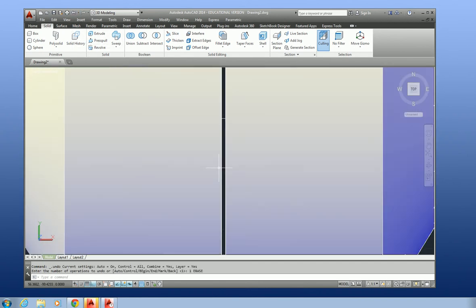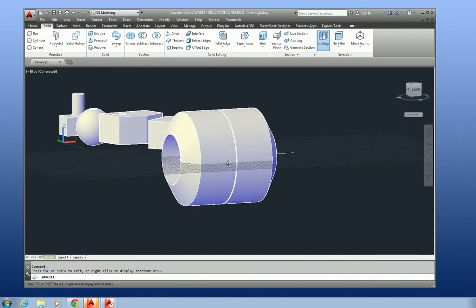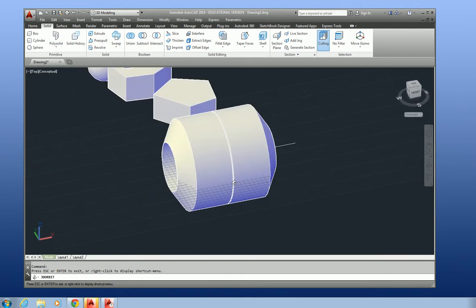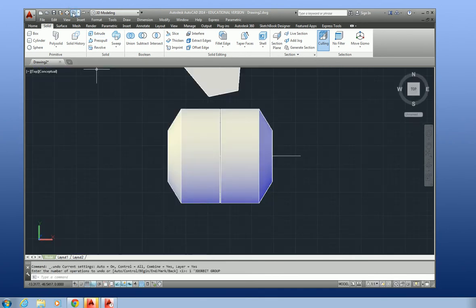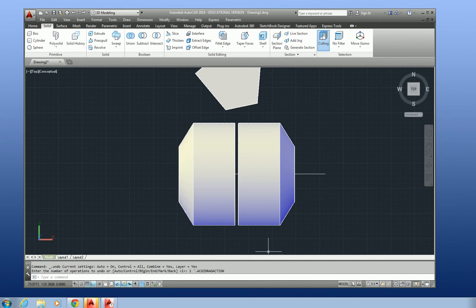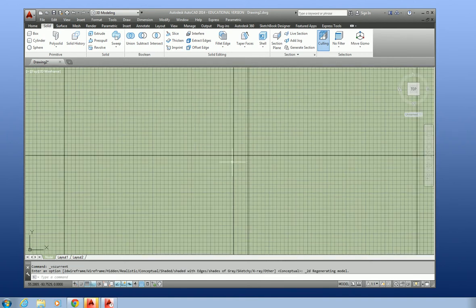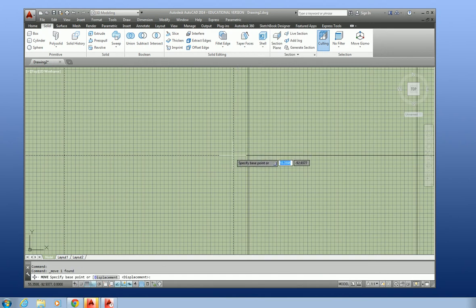Now also notice that they're not connected. This is a common issue with the project in Chapter 9, is they don't successfully connect with one another. Okay, you want to make sure that they are actually connecting. Let's back up a little bit to the part where I moved it. When you go to move this, it's a good idea maybe to change it into wireframe. Okay, and then come in here and move it this way. There you go. Now you know you're connected.